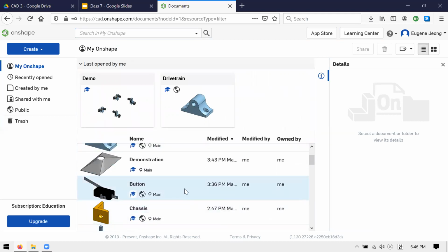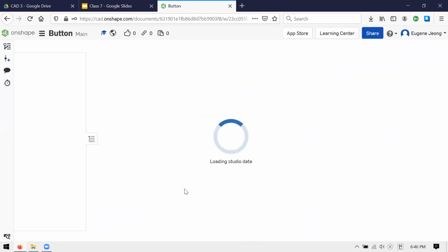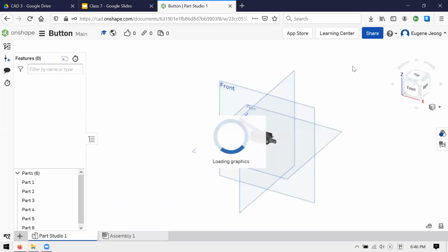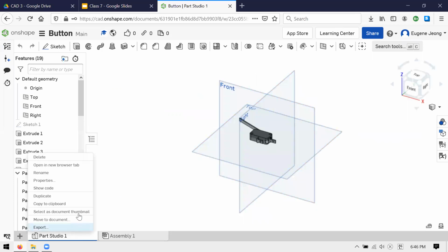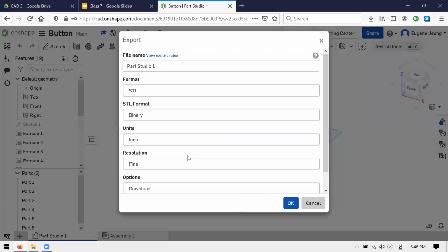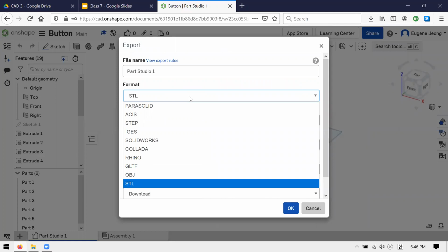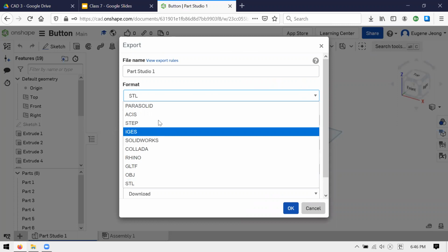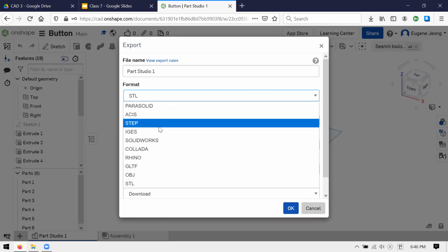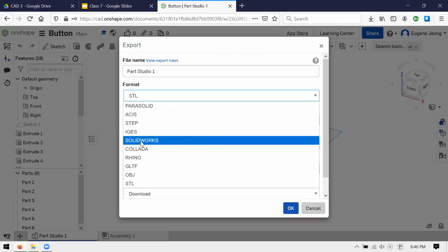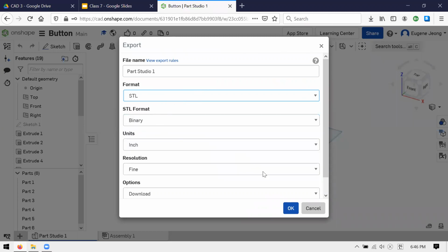What's a bit more relevant maybe is if you want to share a CAD that you made with someone else. The first way to do it is obviously, as we talked about before, you can just export your files and save the physical file onto your computer. There's STL for 3D printing. There's STEP and IGES, Parasolid, which are very common if you know someone who uses SolidWorks, of course. So you can just send them the actual file, maybe by email or server or flash drive.